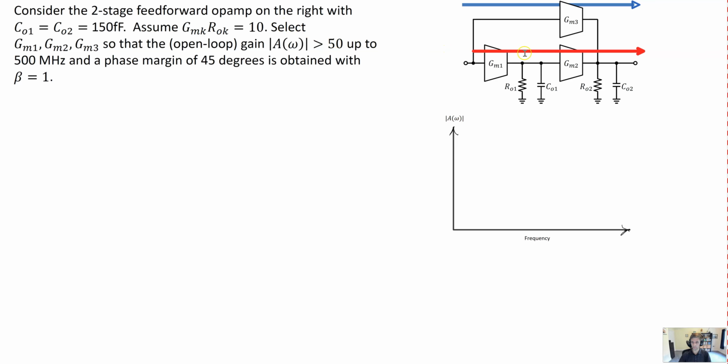First of all, we're going to focus on the red path through the amplifier here, which is a second order path. That's going to provide most of our gain in band. So that's obvious. The response through that path, being second order, is going to be constant up to some frequency, and then roll off thereafter with a slope of 40 dB per decade.